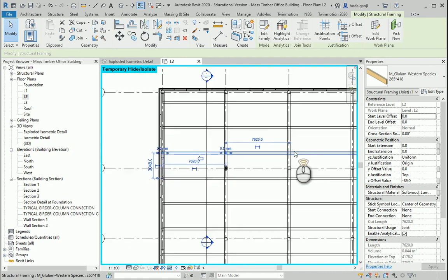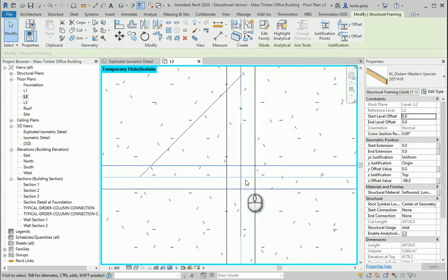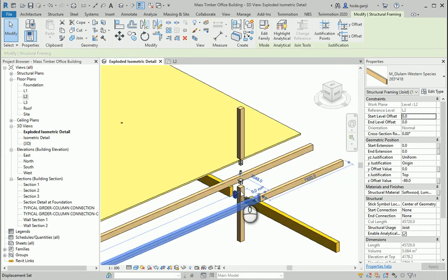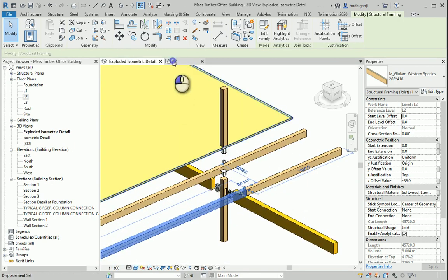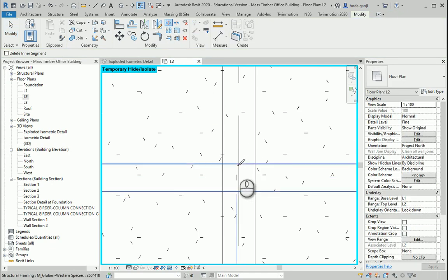So you see now that's the part on that side, and this is a part on this side. Maybe I will repeat the same for here because we still might see this part. Let's check it. Yeah. So I'm gonna make sure to unpin the purlin first, then we can split the element.